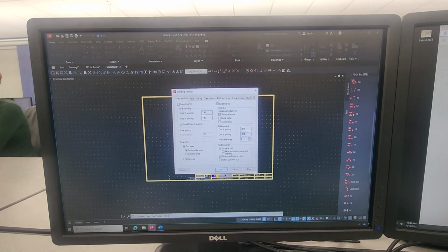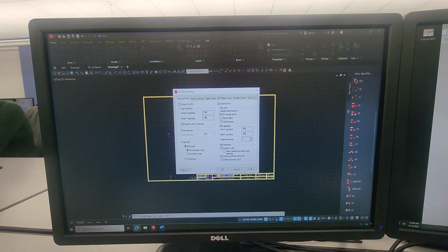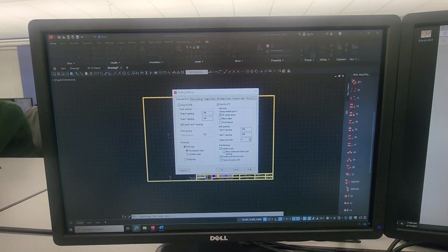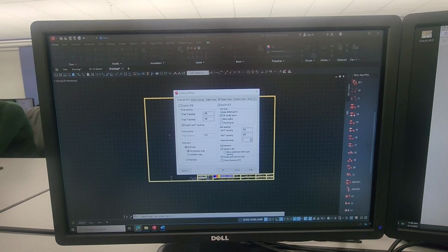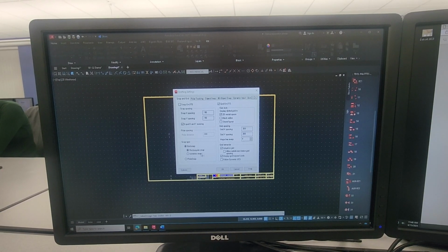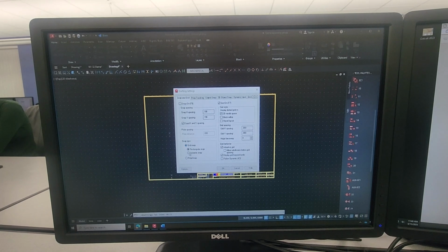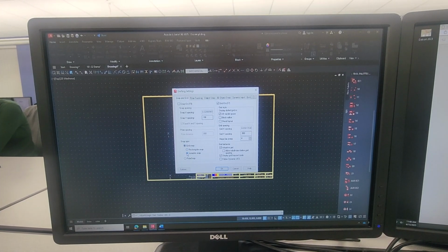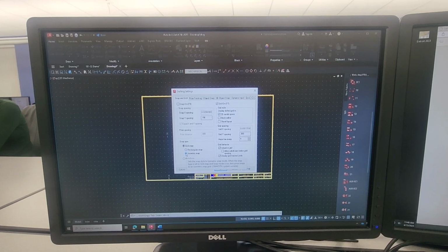Now, down here, what we need to do in order to set this to isometric, so we can do isometric drawing on here, we have to do a couple of things. We have to change our snap type to be isometric snap, and that's right here. See where my cursor is moving right there? It's set to rectangular now, and I'm going to switch it to isometric. Now, you don't see any change happen on here at all.